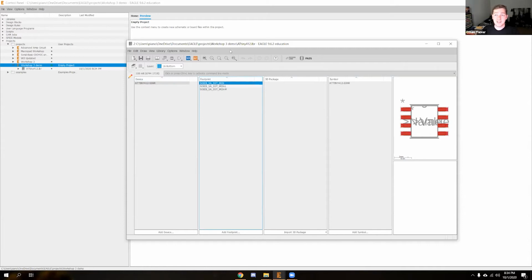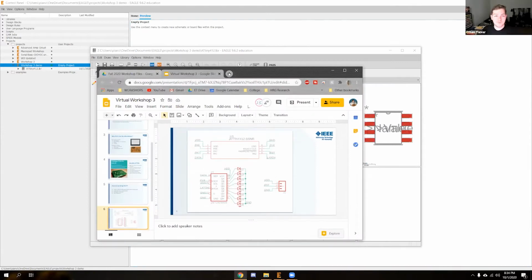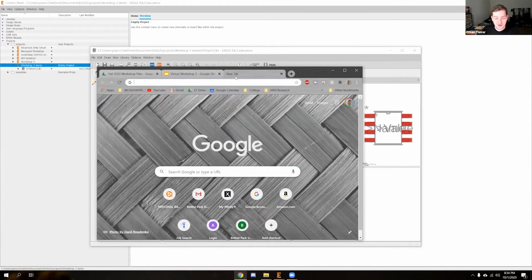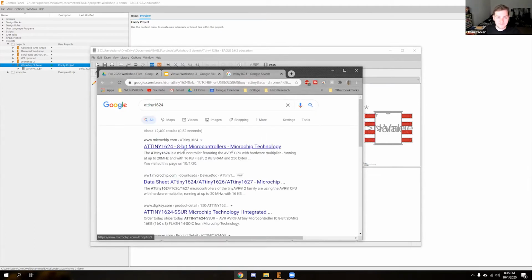So once you have that saved, yeah, what's your question? So what if you want a different device? How would you find that? Like you provided us with that library file. That is a great question. So let me go ahead in here and do ATtiny 1624. All right. And then I'm going to go to DigiKey for this one.